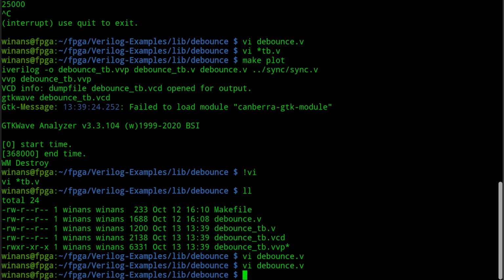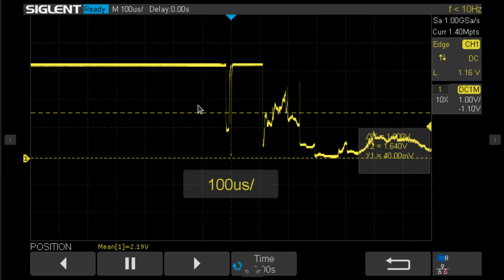So that's a pretty nice generic synchronizer for mechanical buttons pressed by hand. I suppose some crazy gamer might think I can be 10 nanoseconds faster if I modify the circuit so that my falling edge goes out immediately, and then we hold off on the rising edge later on so that when I press my buttons, the computer knows about it before somebody else whose synchronizer works by delaying symmetrically on the falling as well as the rising edge, right? That might be a thing.